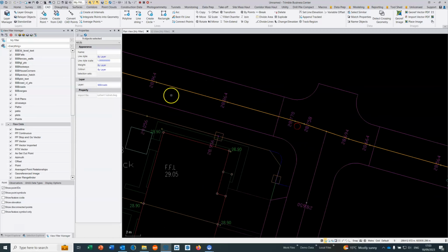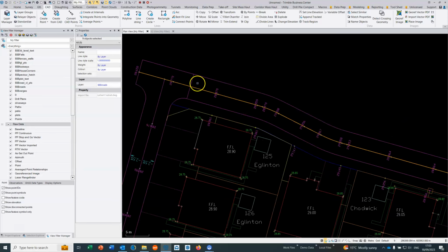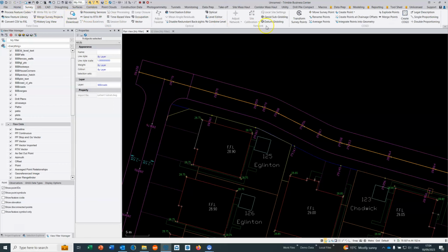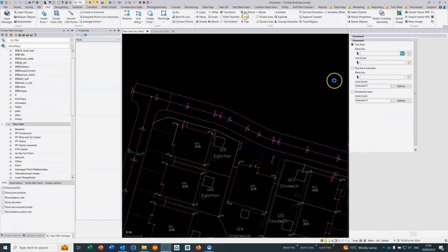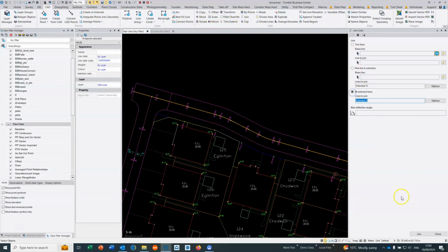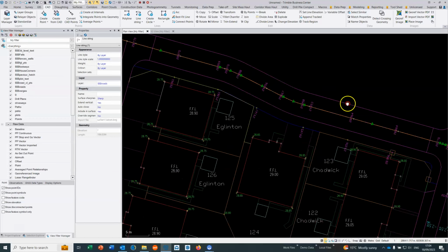So I'm using Control and Click to select all these centre lines. I'm right-clicking, and then we can choose the join commands, which I haven't actually run before, so we'll just run it the first time, and then we don't need to go looking for it the next time. So it's under the CAD toolbar, join. I'm going to join all selected lines, and as long as they're all connecting, then they will join up.